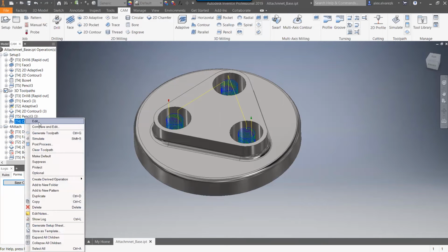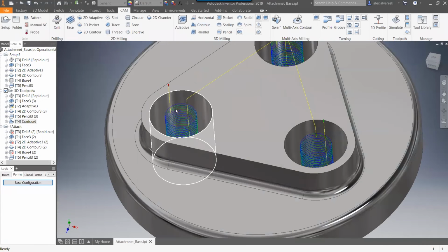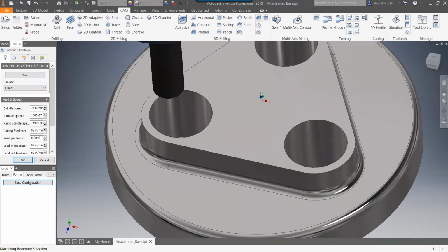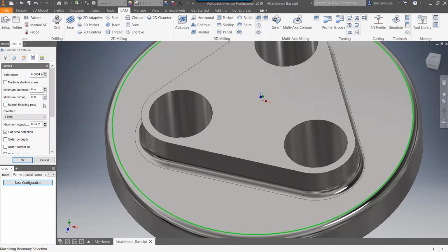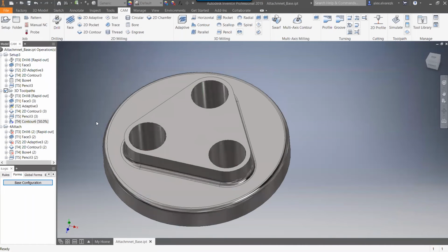So let's go ahead and fix this toolpath a little bit. So it's actually a good looking toolpath, right? Not bad, but it can take larger step downs. So let's go ahead and control that by going to the passes. Maximum step down, let's say it's going to be 0.75. That was probably a little bit too much. So we can go down a little bit.